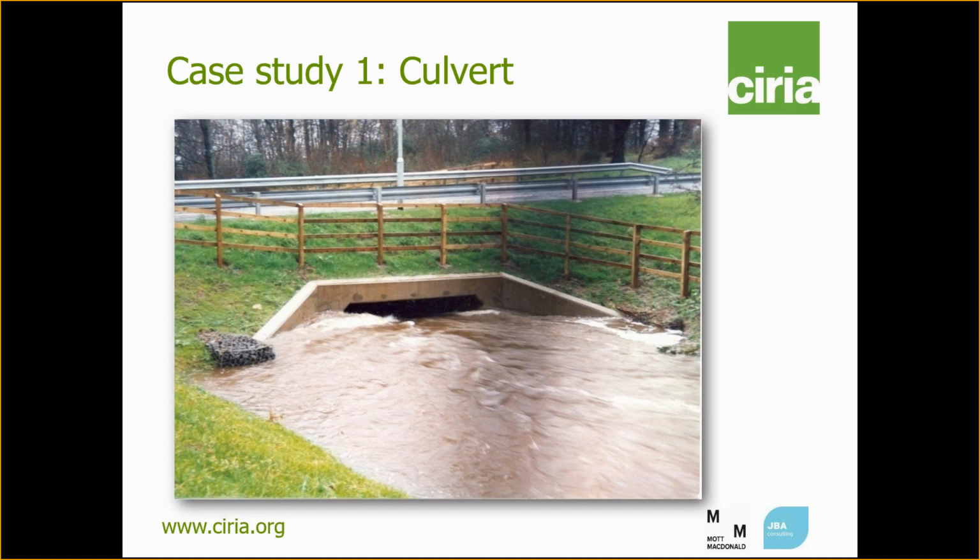Although you can't tell directly from this photograph, this culvert is short, it's only the width of the road, it is straight, it doesn't change section. And finally, in terms of the high flow operating performance, above the culvert, the road level has been lowered to provide an emergency overflow route.